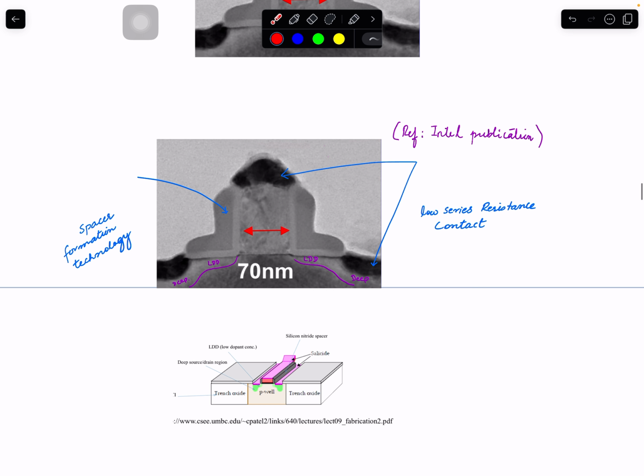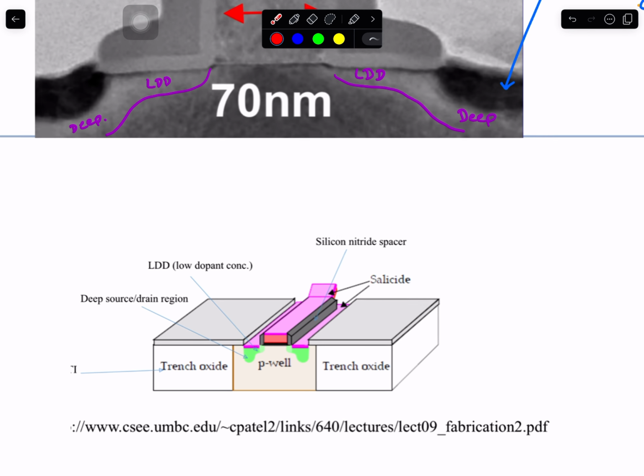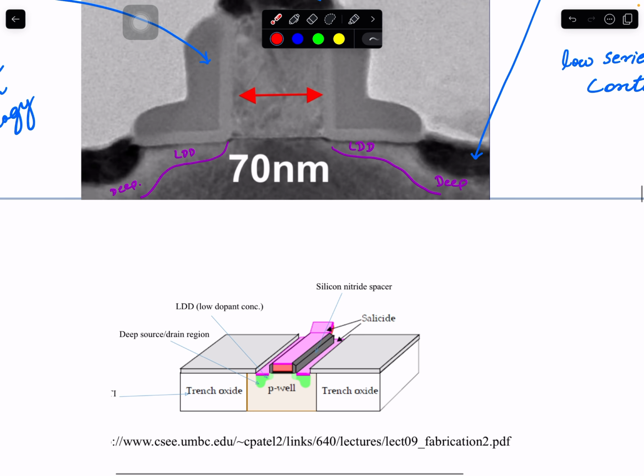Okay, this explains it a little bit in a three-dimensional way. The same thing is up there. So this is an NMOS, it's a P-well, right? And this is that diffusion, and this is the gate width. This is the length. You see the diffusion.